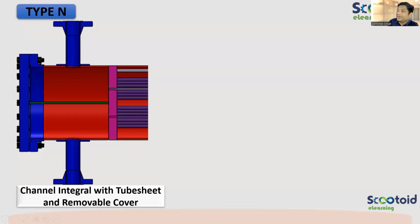There is no bolting at all for the tube sheet. Here also it is welded. Here also it is welded. So tube sheet is becoming integral with channel and also the shell side, because the other side is the shell side, right? So integral with both, with channel and with shell. Great.